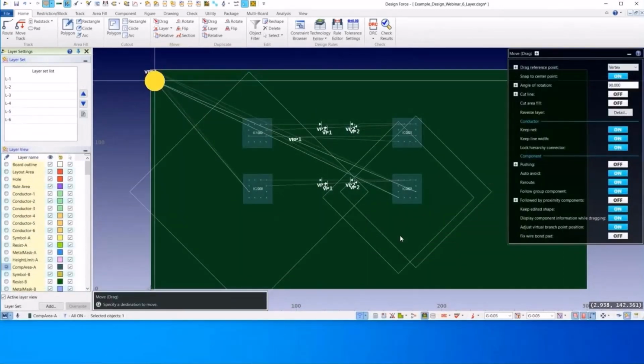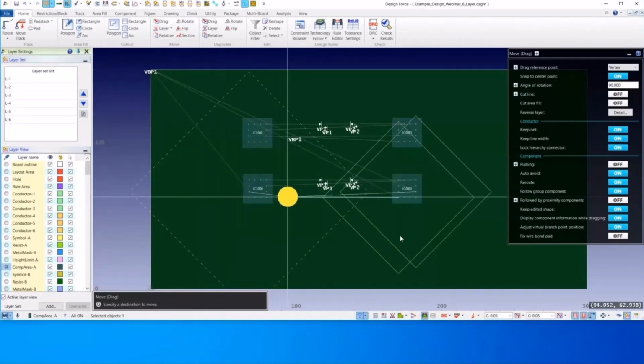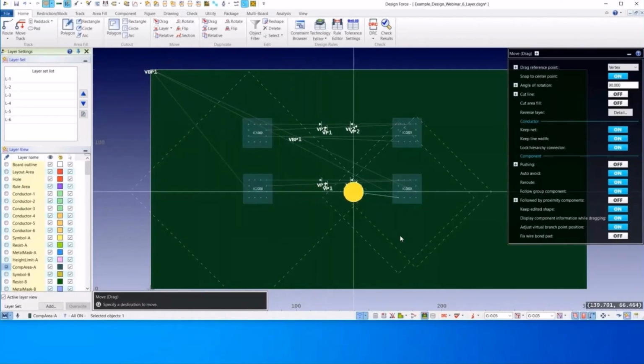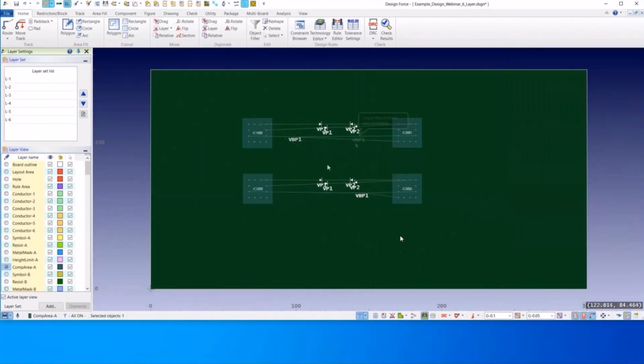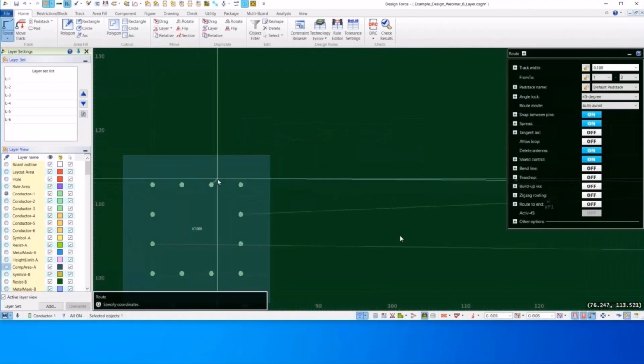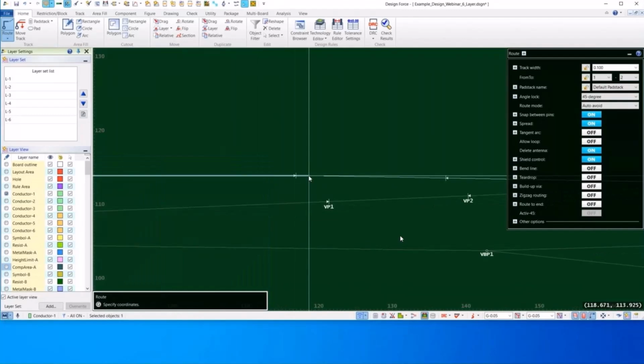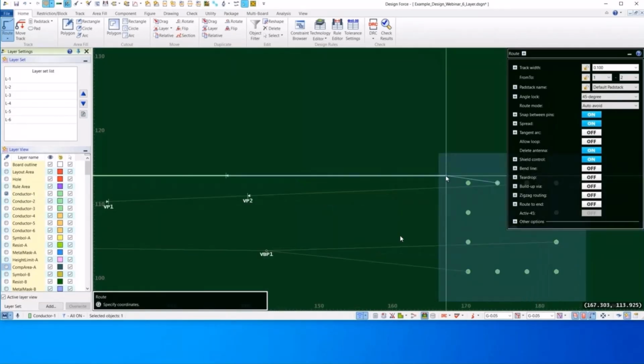Now you'll notice the constraints for the signals and topology are marked by the tilted squares. And now we can see when we move into them that the impedance requirements are being met. And then we place it over here. Now we begin routing the signal following the topology, which, as a reminder, includes 3 different transmission line widths. So we put the first one, this is the second one, and then we finish it.